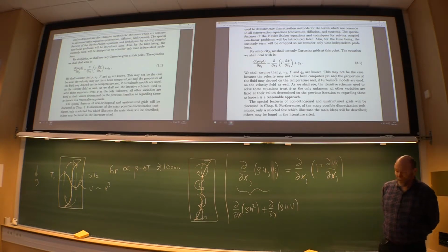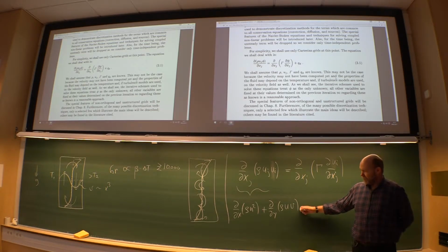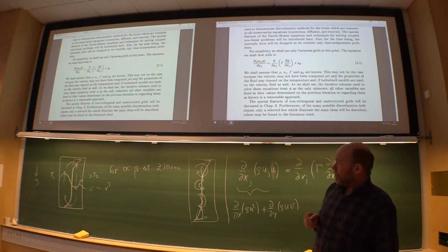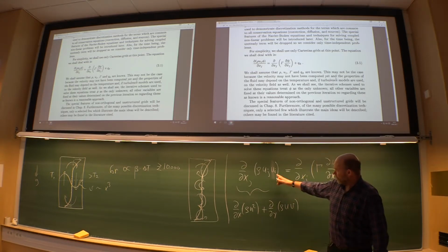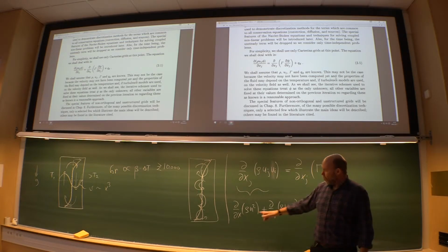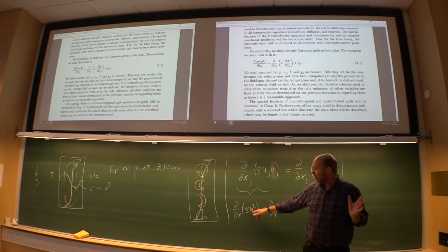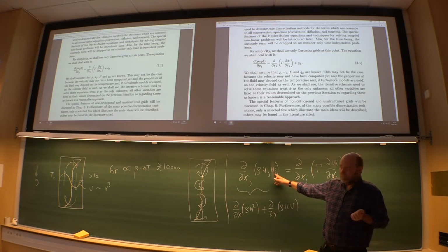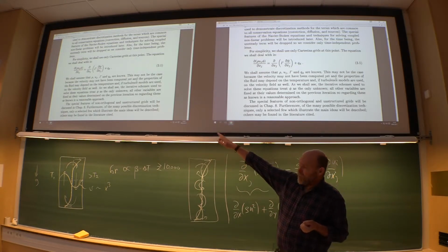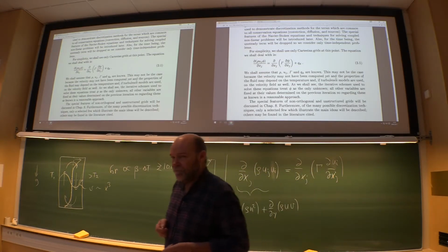So yes, definitely strong form, and to achieve it you have to use the continuity equation. We saw that already. Also, when we keep it in this form, using a generic unknown phi, we have actually linearized this term. So there, one of these velocities, that is this one. The other one is our unknown phi. So here you have a nonlinear term. Here is linear. So you see the cheat. Very easy.